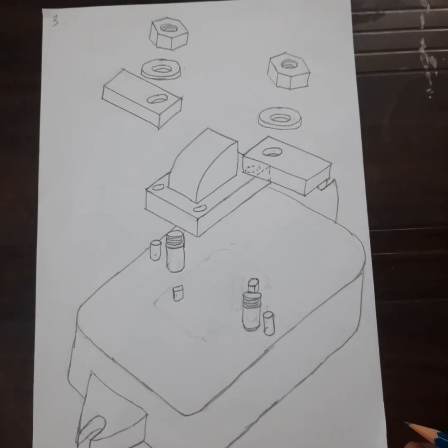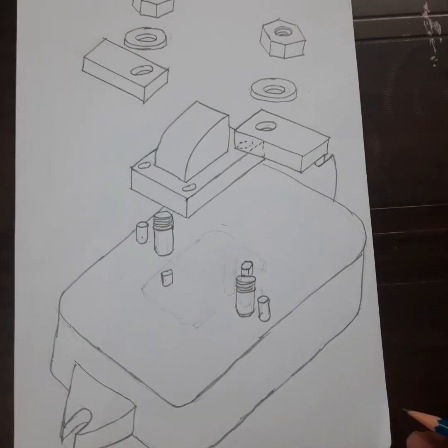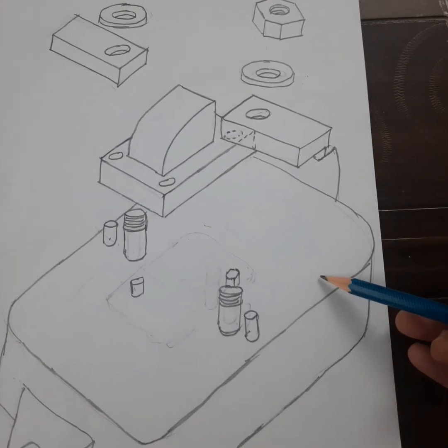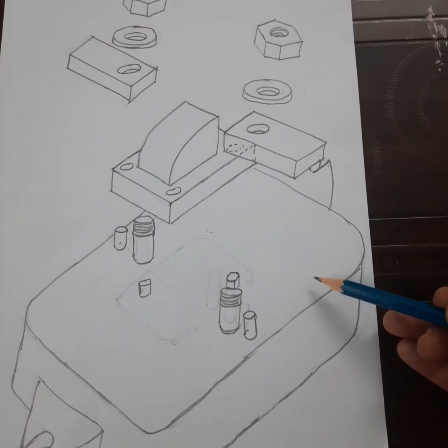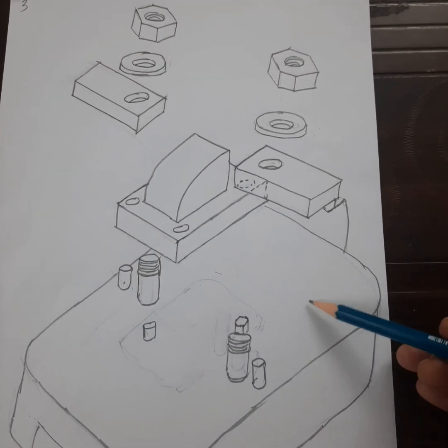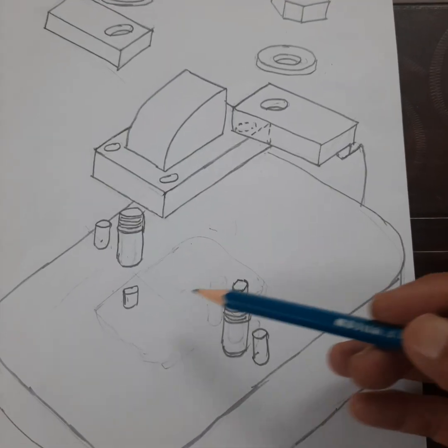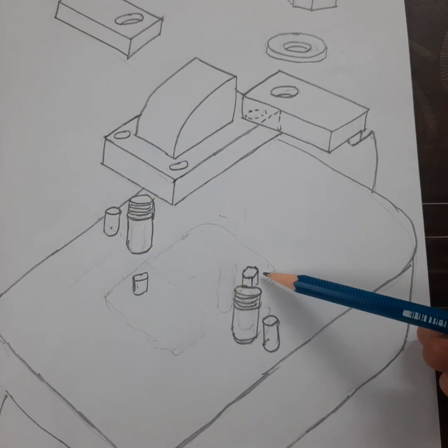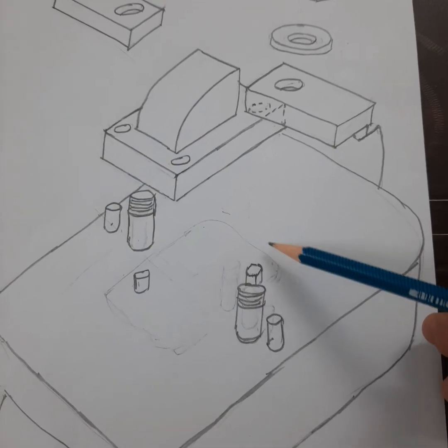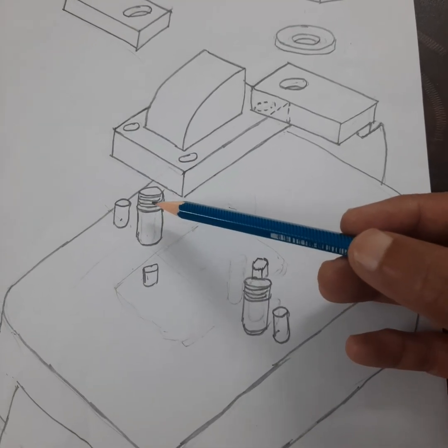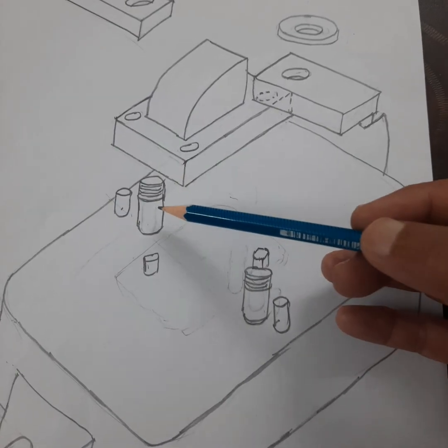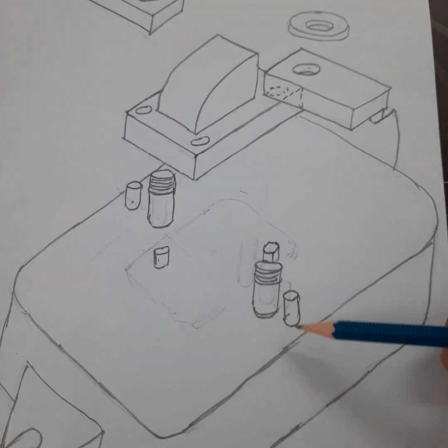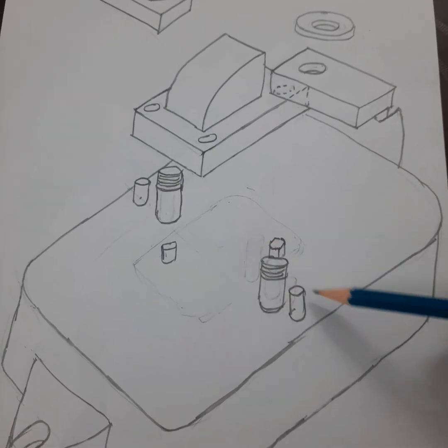So this is the exploded view of the milling fixture. There is a base on which all the other elements are to be mounted. On the base, we provide one round locating pin and one diamond locating pin for locating the component. For clamping purpose, we are fixing a stud on the base, so 2 numbers, and there is a heel pin, 2 numbers, which are fixed to support the strap clamp.